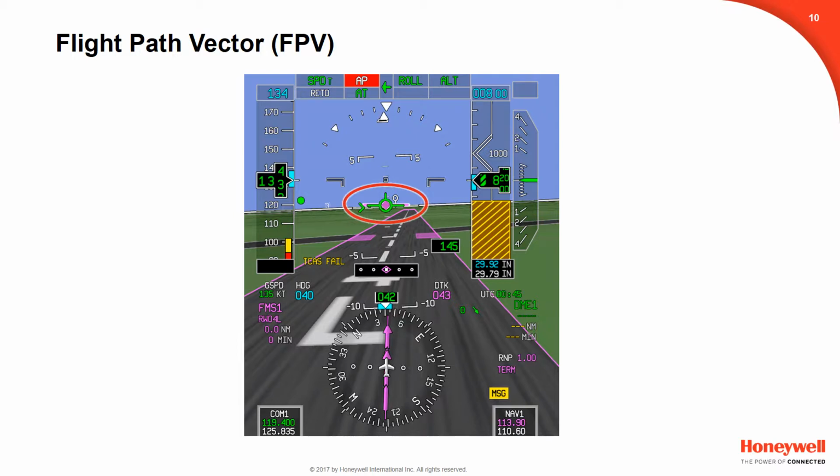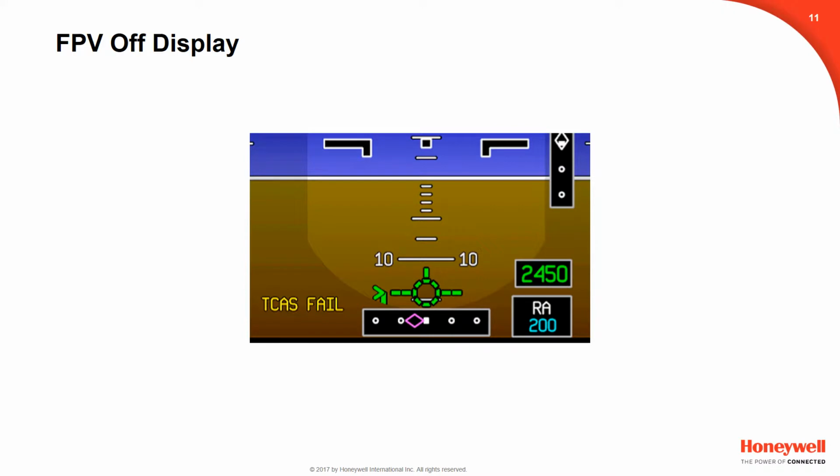The Embraer SVS utilizes a track-centered design which provides the pilot with an immediate knowledge of the trajectory of the aircraft with respect to terrain. This means that the display is oriented to flight path and not heading. This design prevents symbology collision and occlusion of airspeed and altitude tapes by the flight path vector during high crosswind operations. When the flight path vector position exceeds the display limits on the PFD, the flight path vector becomes striped and is placed at the edge of the ADI area, indicating the FPV is not currently showing the actual path